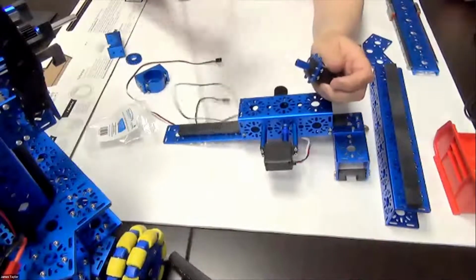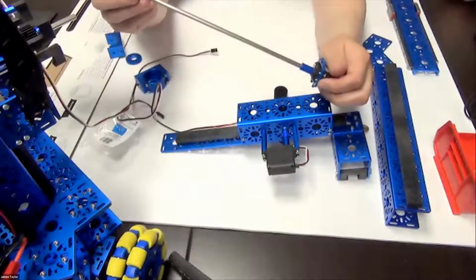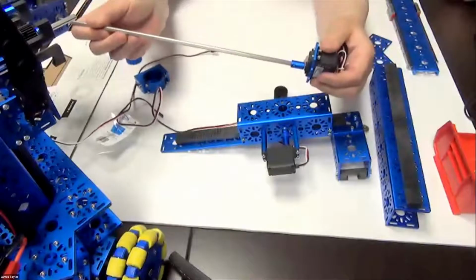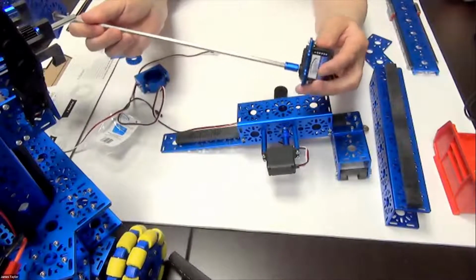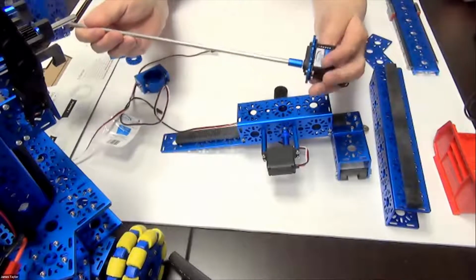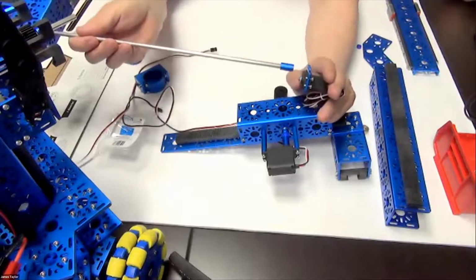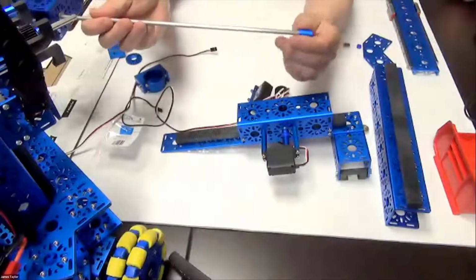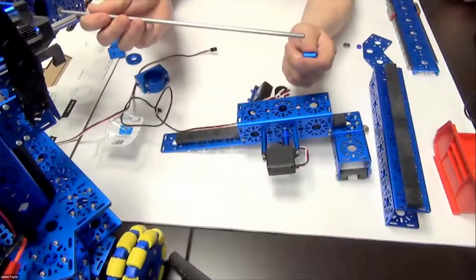All right, and with that, that's where your shaft is going to go in, right? And there is a set screw point on there for you to put against the flat of the shaft adapter so that you can translate the motion, right? So you can use spacers in there as well, because you don't want any play this way at any time on movement, because that causes it to come loose, all right?